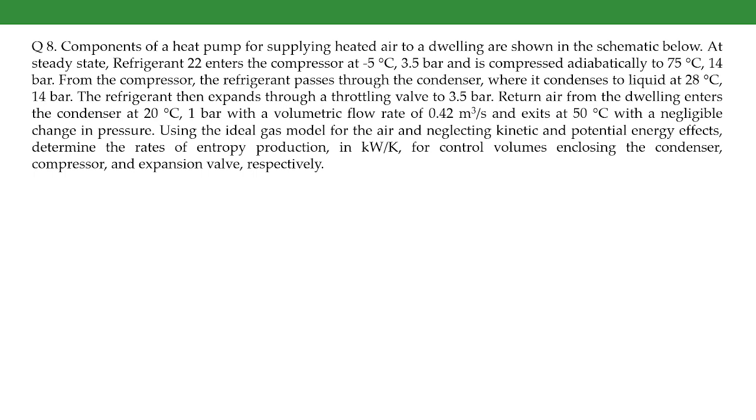Okay, so the components of a heat pump for supplying heated air to a dwelling are shown in the schematic below. So I will be drawing the schematic. At steady state, the refrigerant 22, R22, enters the compressor at -5 degrees Celsius and 3.5 bar, and it is compressed adiabatically to 75 degrees Celsius and 14 bar.